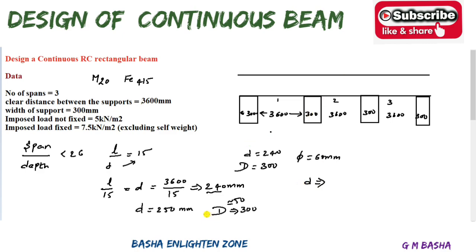Then after choosing this, assume the width to be around 230 mm. Here I am taking the width less than the effective depth, otherwise you can take 250 also, no problem, but then both will be equal. It will come more or less as a square section, but D will be higher only, no problem. So choose the width of the beam as 250, 240, 230, whatever you want.